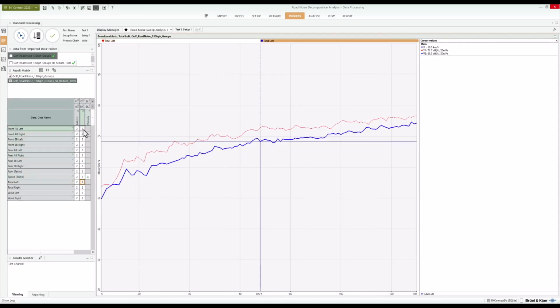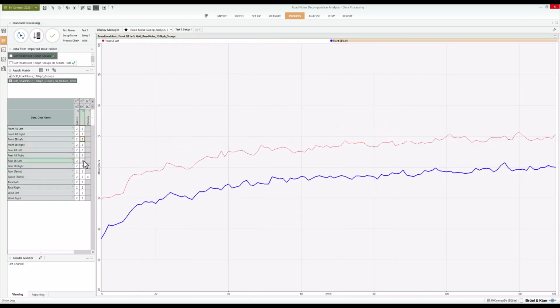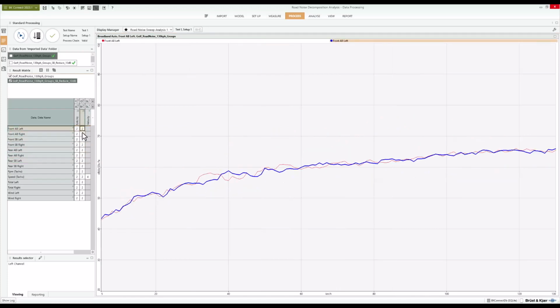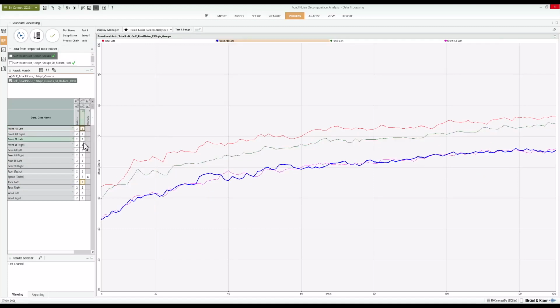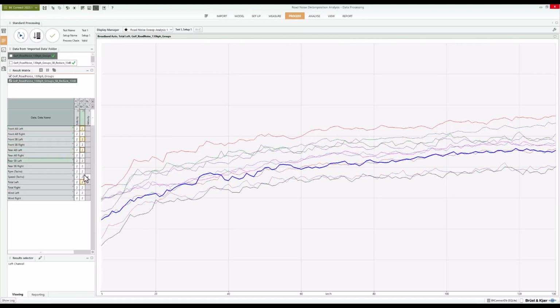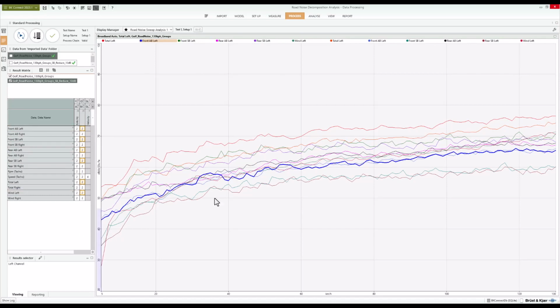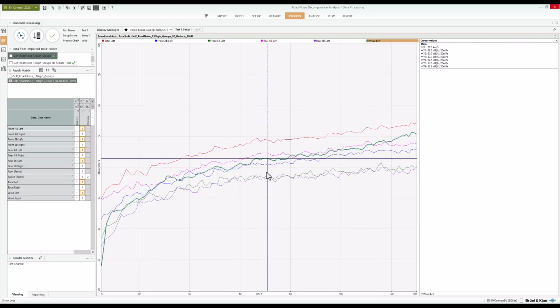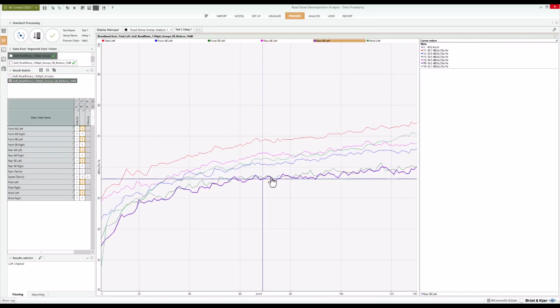So that's quite easy. If we go down to the individual groups, we should see that the structure-borne groups are indeed reduced. But if we go to the airborne groups, we don't see any reduction. We really see that same performance across, which makes sense because we know we've only changed in the model the structure-borne components. So we've confirmed both objectively and subjectively that reducing the structure-borne components has a major effect. However, 10 dB, if we're looking at these, we've got our new contributions for the structure-borne. They're now way below what the other contribution groups were.